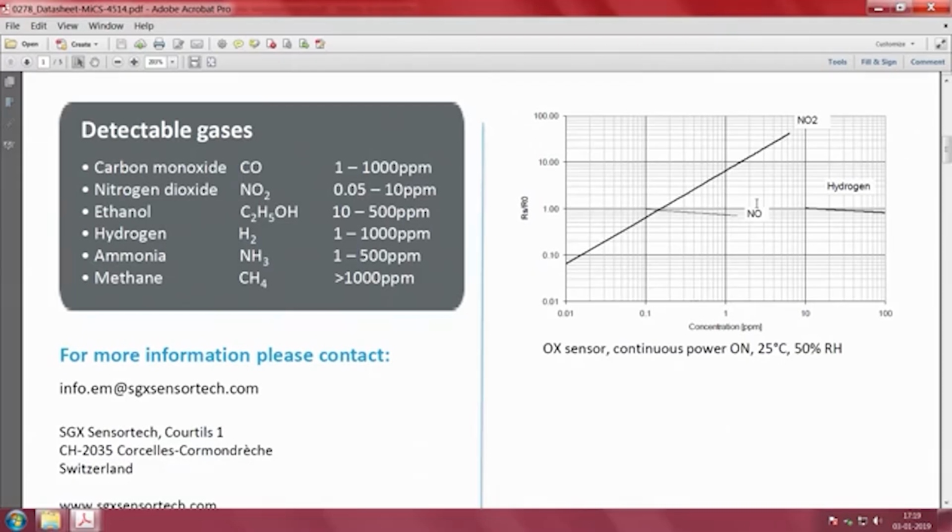Look at what all he has put down as a spec. TPH, if you see, I think he has taken pressure as 1 atmosphere, so leave that. P is done, temperature is 25 degrees, H is 50% RH. So now you go back and look up what should I do when I have to calibrate this in a calibration facility. What will you do?